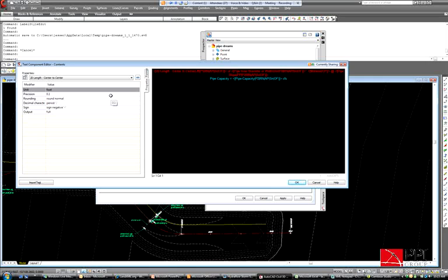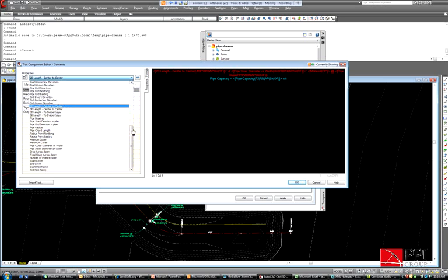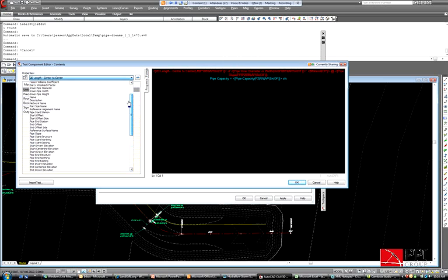Precision becomes important. You've all seen out of the box, we've got a couple decimal places there on our contour labels, which is still there in 09, unfortunately, but this is where you come in and change that on the contour label styles. Now that I've written that expression, I can come in here, and under the properties, that pipe capacity expression is available to me.